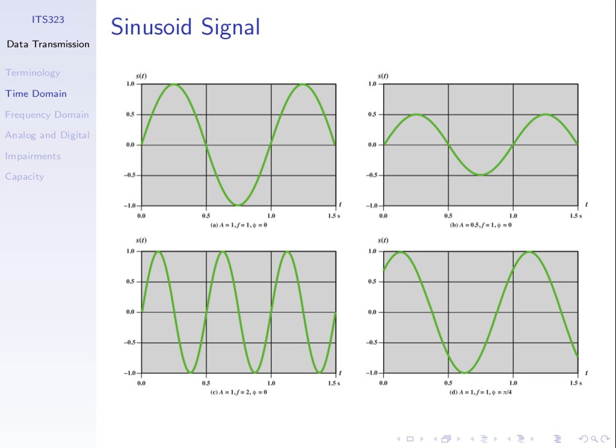Visually, the phase shifts the signal along. Take the original signal with a phase of pi over 4, you can imagine that it's been shifted back. So now at time 0 it starts here. It doesn't start at 0 magnitude, it starts at this point, which is 0.7 something. I don't know the value. It's been shifted because of the non-zero phase here. Other than that, the frequency is the same as A. The peak amplitude is the same as A. It's just been shifted along in time.